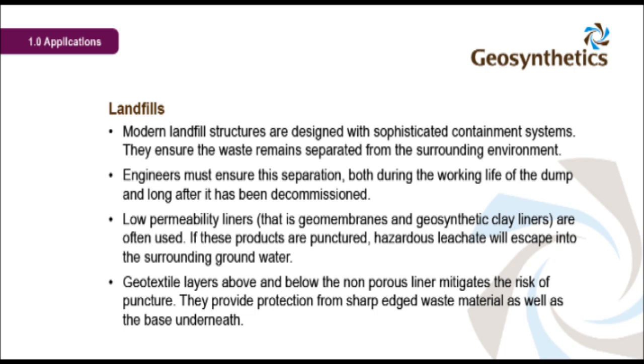Modern landfill structures are designed with sophisticated containment systems. They ensure the waste remains separated from the surrounding environment. Engineers must ensure this separation, both during the work life of the dump and long after it has been decommissioned. Low permeability liners, that is, geomembranes and geosynthetic clay liners, are often used. If these products are punctured, hazardous leachate will escape into the surrounding groundwater.